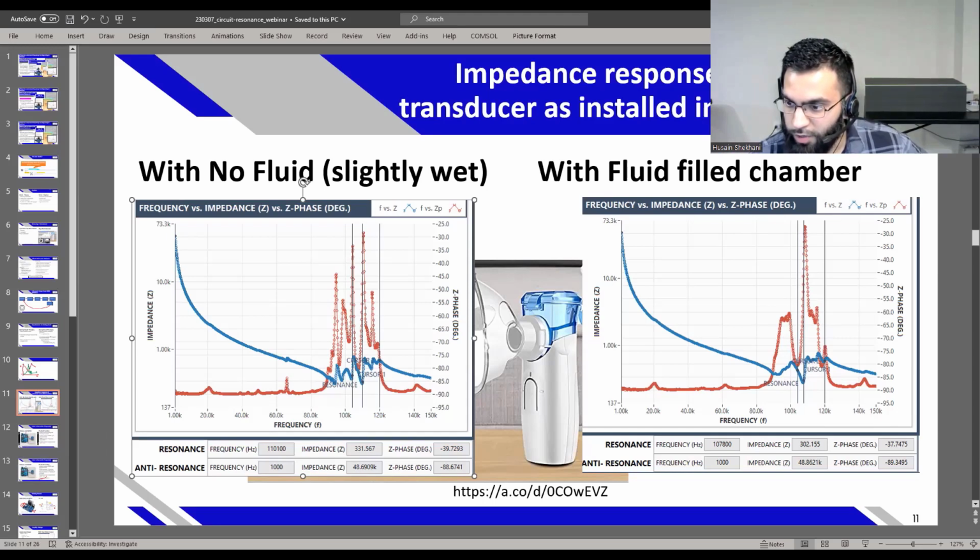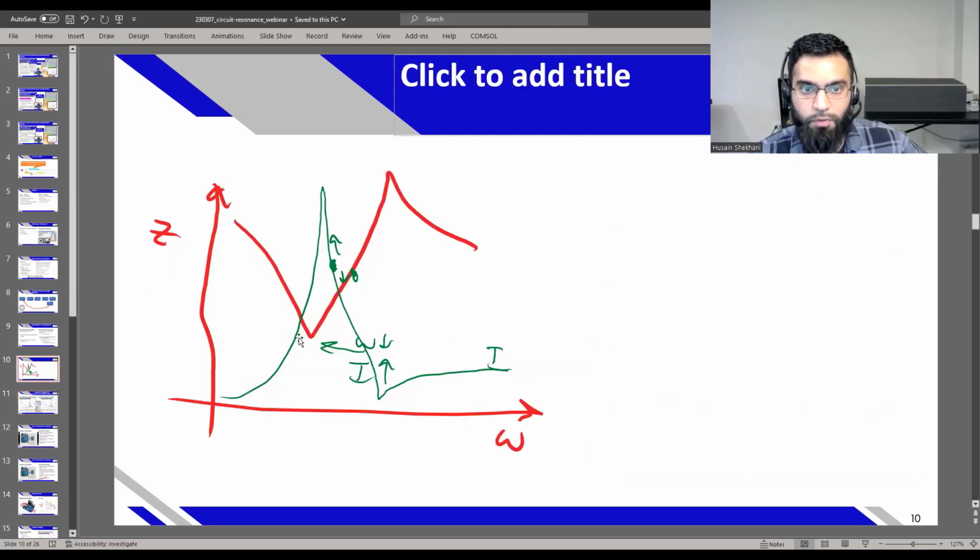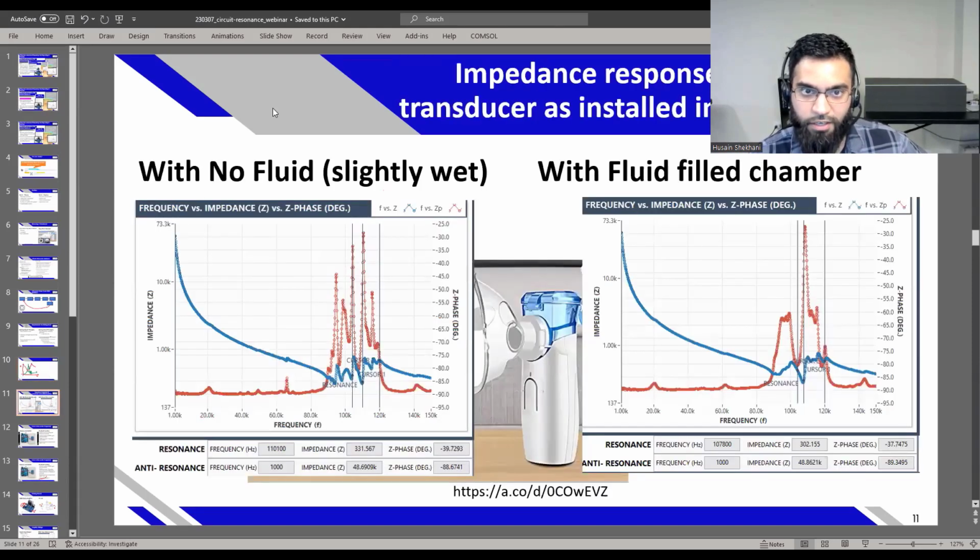There's a comment here: maximizing current would yield electrical resonance, but mechanical resonance could still be off. Yeah, so in this case I won't be maximizing current. I didn't do a current maximization program, just kind of getting ahead. I did just a set point. So I set the microcontroller to go back and forth around this area once I found the target. The mechanical resonance and the electrical resonance are such a messy response that even if you're drawing power, you're not necessarily creating atomization.